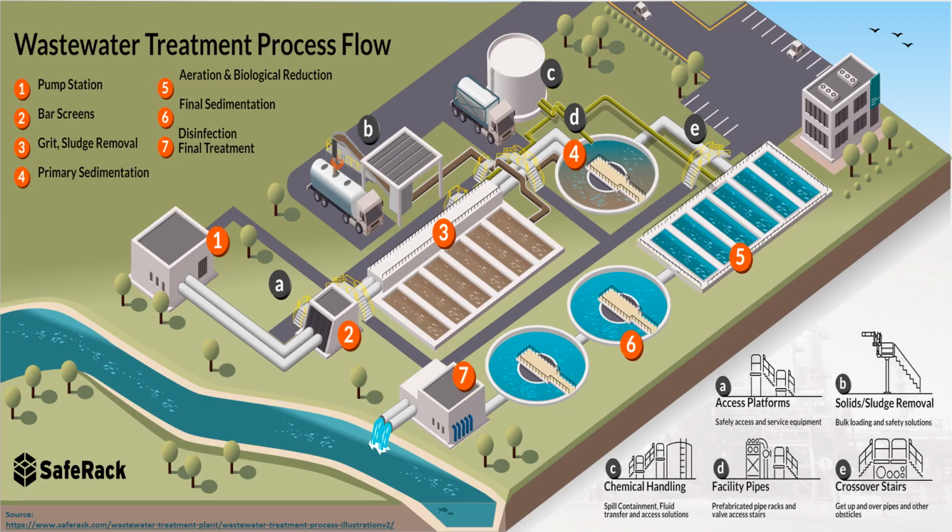Wastewater treatment plants. The major aim of wastewater treatment is to remove as much of the suspended solids as possible, before the remaining water, called effluent, is discharged back to the environment. As solid material decays, it uses up oxygen, which is needed by the plants and animals living in the water. Primary treatment removes about 60% of suspended solids from wastewater. This treatment also involves aerating, stirring up, the wastewater, to put oxygen back in. Secondary treatment removes more than 90% of suspended solids.